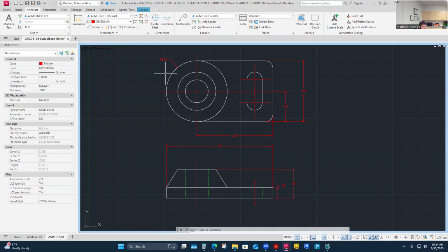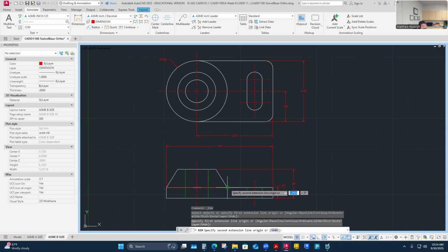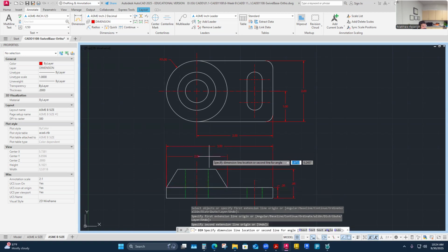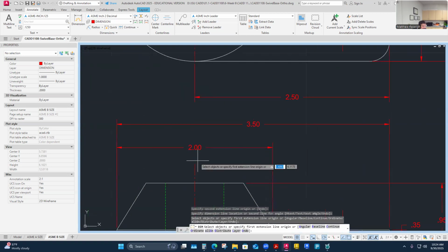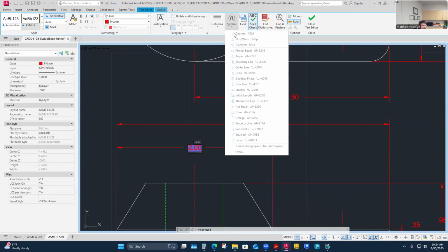But that's confusing because you're like, well, the radius is the diameter. Yeah, it is. But remember, the radius that I chose with an R is because the base plate's a radius, not a diameter. But when I look at the cone, it has a diameter with it. So I think I might add a linear dimension that's a diameter right here. That's where it appears in its rectangular view. It's a nice snap dimension. It just needs the diameter symbol in front of it.